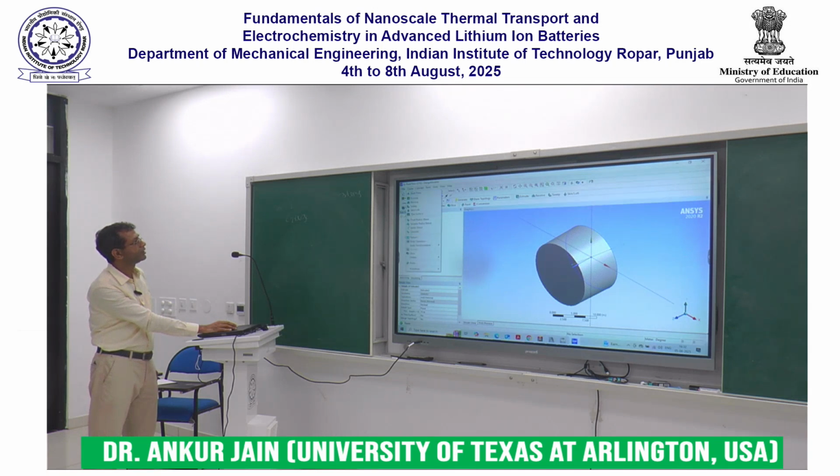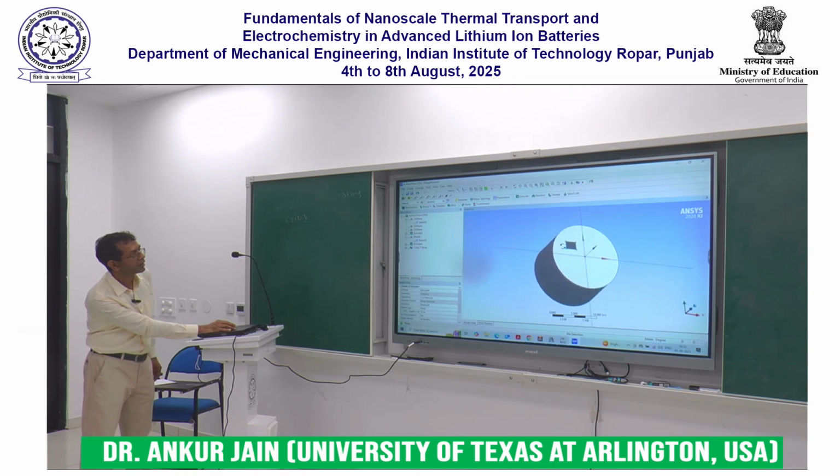Let me create a new plane from this face. I will look at this plane and create a new geometry of a rectangle. What I'm trying to do is to make a hole in this cylinder. So for that I'll create an extrusion based on this sketch, and instead of adding material I will say cut material, and you can see that I now have a hole in this cylinder, right?